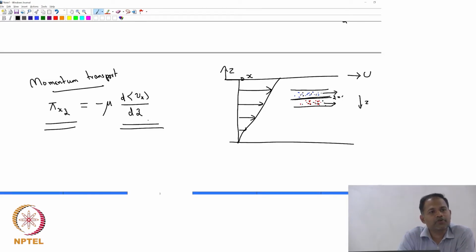It is just the way you would have done your heat transfer. In your heat transfer you have learned Fourier's law of heat conduction. You have learned, yes, no? Heat flux is proportional to temperature gradient, right? You would define it as heat flux equal to some diffusivity times the temperature gradient, and the heat flows in the direction of decreasing temperature. So, similarly here the momentum gets transported in the direction of the smaller velocities. That is why you have put this negative sign, to recognize that fact.